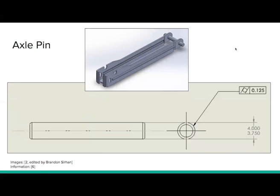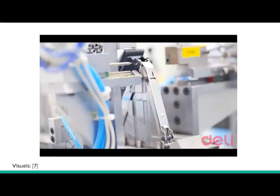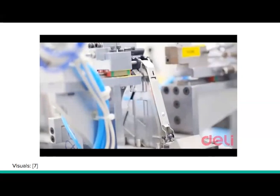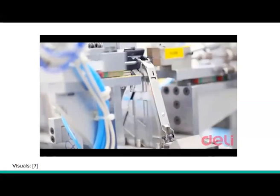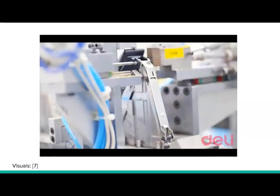In order to control the form of the pin, we chose to use cylindricity. Cylindricity is a common GD&T control applied to pins and important cylindrical parts. It is especially important when functionality relies on roundness of the pin and straightness of the central axis of the pin. As these mating parts are likely manufactured with loose tolerances, it is necessary to ensure that the diameter of the pin will always be smaller than the diameter of the hole.